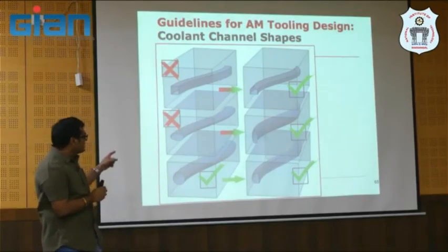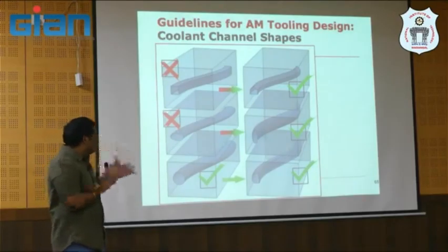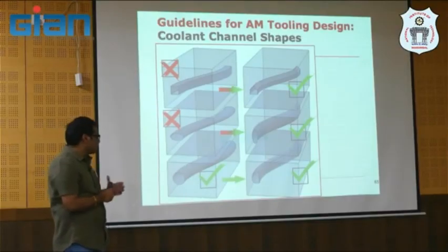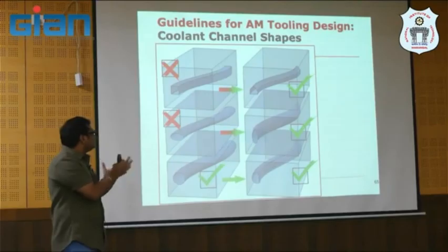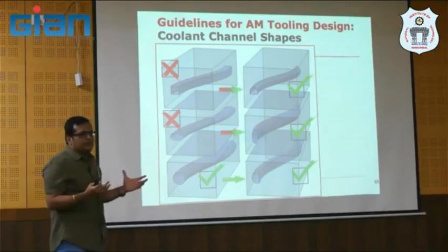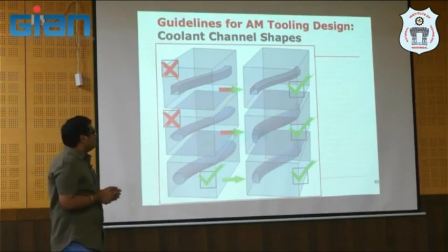You can try simulating with different cross sections. You try elliptical, oval, or a ribbed one, or a trapezoidal kind of cross section, right? So you can come out with the optimal cross section of your conformal cooling channel.